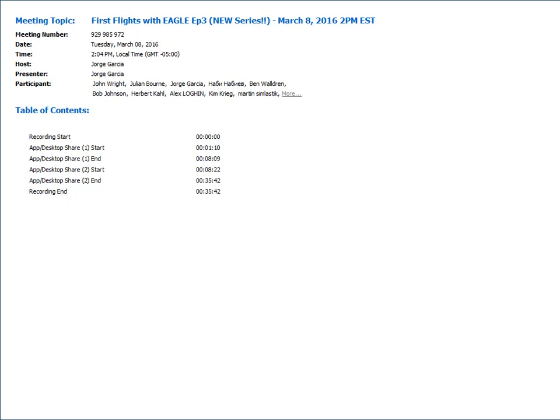Welcome to First Flights with Eagle, Episode 3. So far in Episodes 1 and 2, we have covered making a schematic and making a board. In today's episode, our goal is going to be generating the manufacturing data. That entails a bill of materials and Gerber files. In some cases, it entails something called a pick-and-place file, which goes by a few other names, such as Centroid or XYRS file.